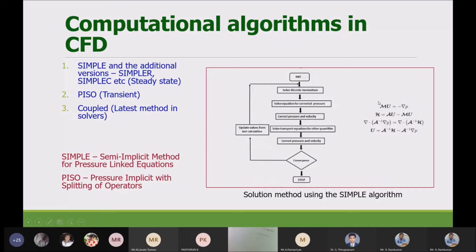That is the point. So basically, you're calculating one thing using one equation, substituting in the next, seeing if both the values are equal. If not, then the cycle repeats. And once both of these equations are satisfied, both continuity and the momentum equations, then we'll call the solution converged. That is the point. So this algorithm will help us do that.